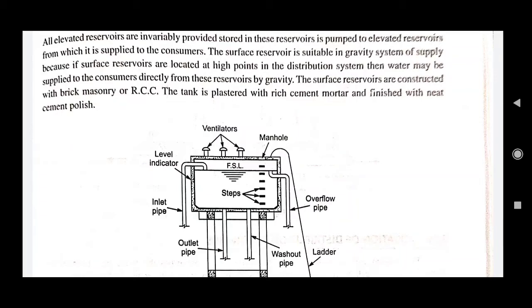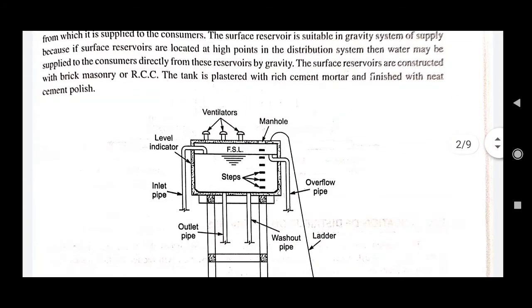That is, at least one pump system is required from the surface reservoir to the elevated reservoir, so that the water can be stored at a certain height. There is also an overflow pipe on the top of the tank, because if a larger amount of water is continuously supplied into the system, and it is not manually or automatically controlled, the water can spill over the top, so that the system does not get affected due